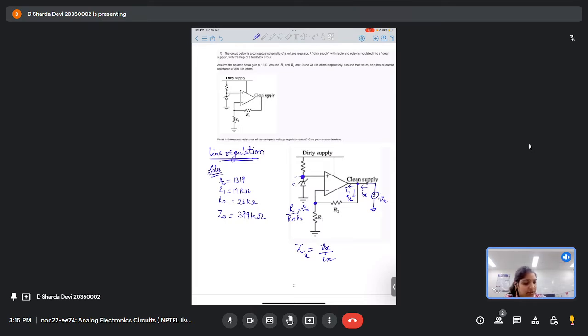If Vx is a small AC signal, you'll see that AC signal in the inverting terminal, but the non-inverting terminal will not see any effect because of this small signal Vx. So it is AC grounded, as we normally say.